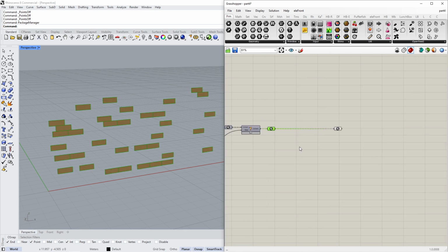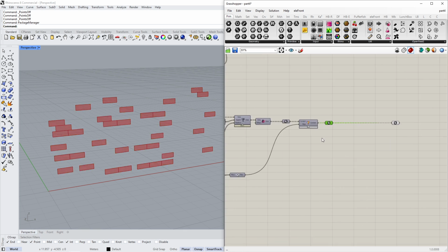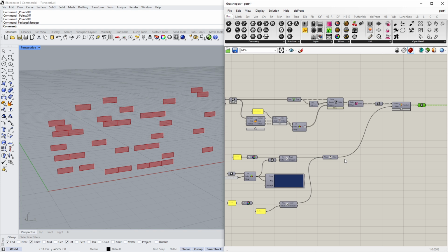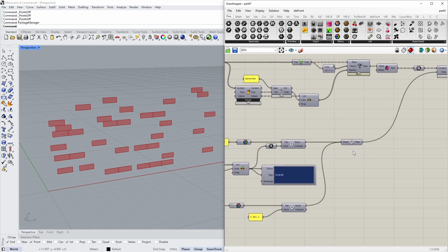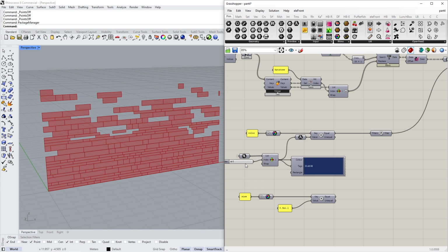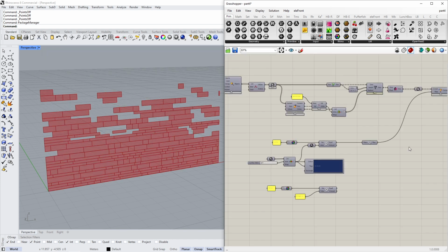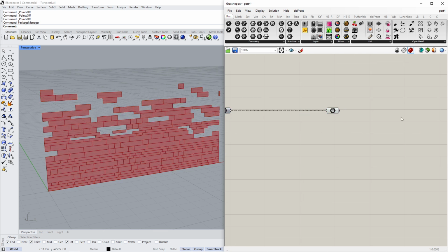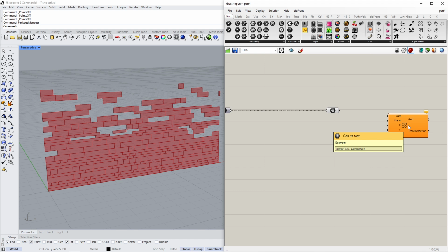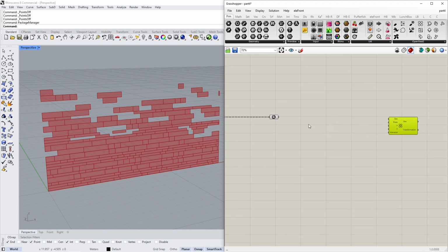So the first thing we're going to be doing is lay out all the tiles we're going to want to prepare for laser cutting, right? So let's say, again, instead of doing all the tiles at once, I think it's wise to maybe sort them by color. So right now I've selected the first color, the dark blue. So let's start with those guys, which are these. And the first component we're going to be using is pack objects. And this component will lay all these objects in rows.